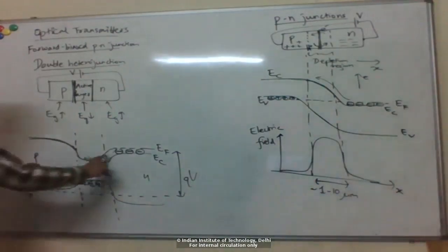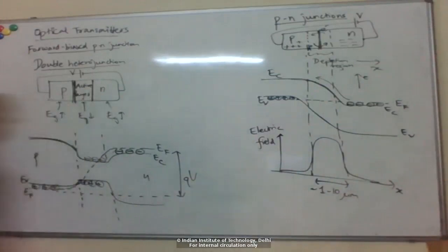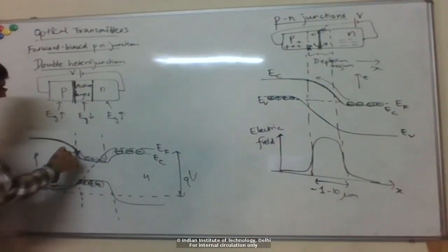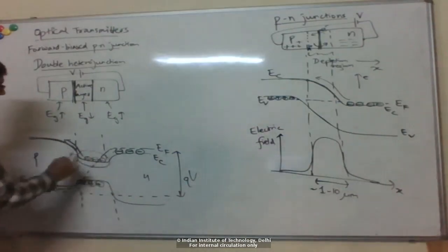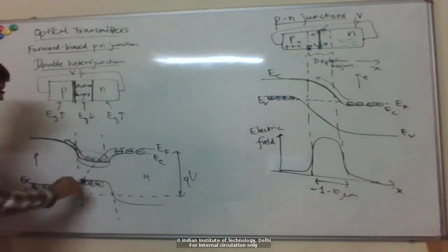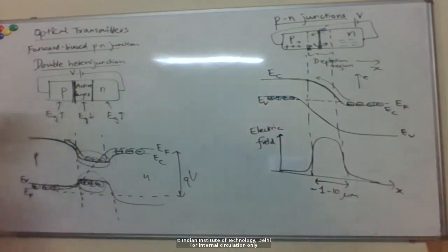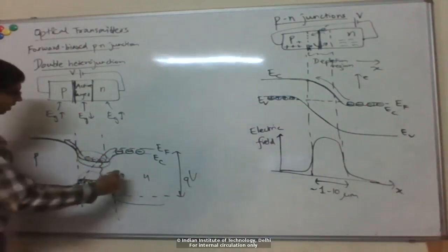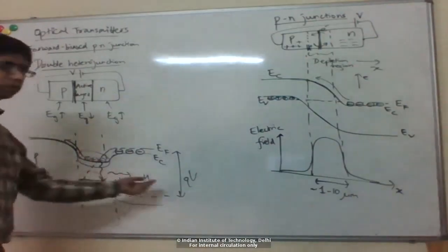Okay. So this kind of barrier which is created, you can see, is basically the difference in the band gaps of this material versus this material, right? So now the electrons can't simply rush through to the P region; they have to cross a barrier. So basically, they spend more time here, right? So it's sort of like they're sitting in a well now. Similarly, the holes. Okay, so they spend more time here in the active region, right? And what this does is increase the probability of radiative recombination, right? So that more of them recombine to emit a photon.